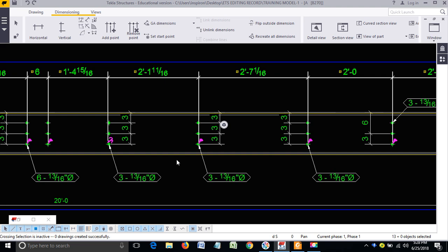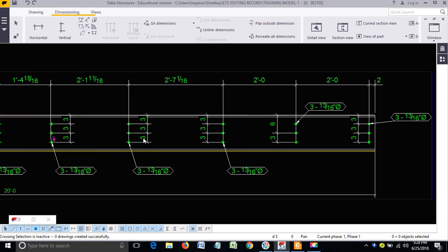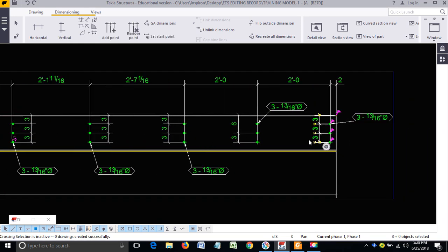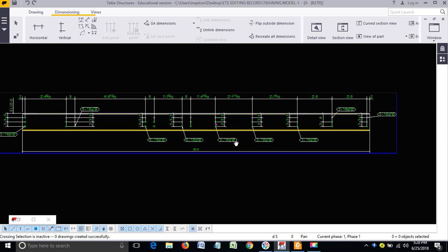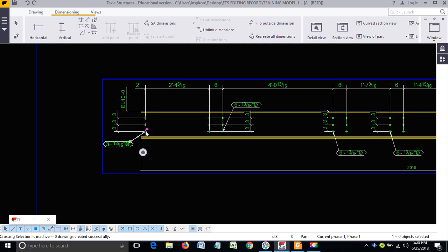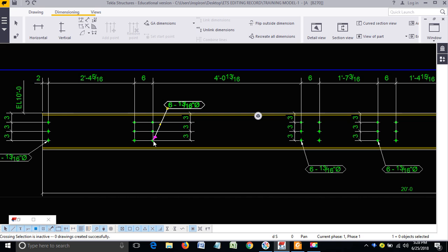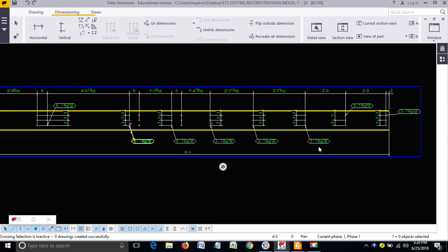Okay, yeah. See, the modeler has done good modeling, and this is the final output. It should be very correct. If you come to here also, the dimension should be outside, not kept on the left side. It should be on the right side. And the bolt marks, hole marks, he kept one down, one on top, but if you want to keep them on top, this point should be shifted to the top hole. See, there is no proper arrangement.